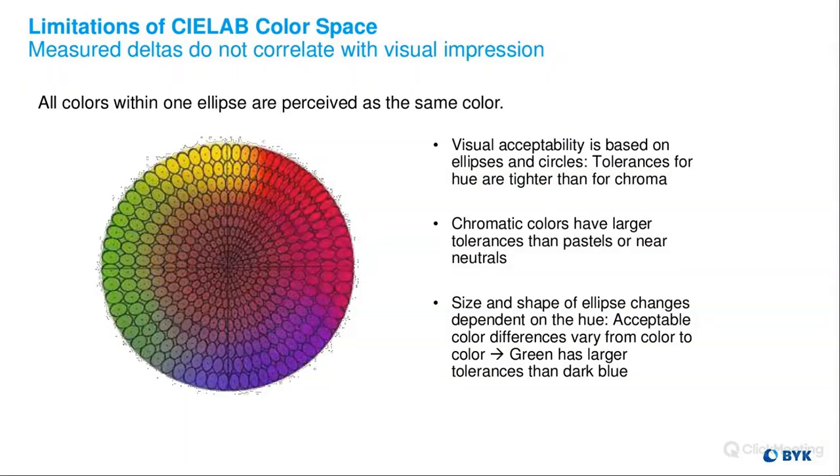But that has nothing to do with how the instrument measures. That just has to do with the texture changing the gloss level of the material itself. So you would still have to have different tolerancing for the flat panel versus the textured panel because your visual perception of the color is going to be different. Yeah, that makes sense.